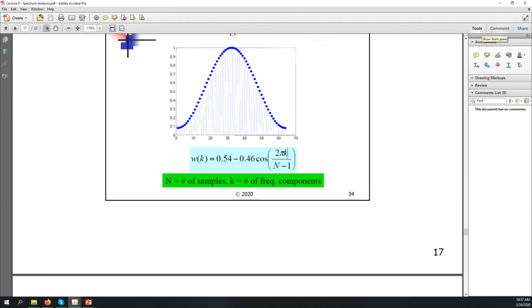There will be some rare cases, like if you'll be using it for a real-time signal where the frequency is unknown, or for any aperiodic signal, where you may not always get an accurate representation, and then you'll have to be trying different windows depending on the type of application you'll be using. So in practice, it depends on the application which window is going to perform better.